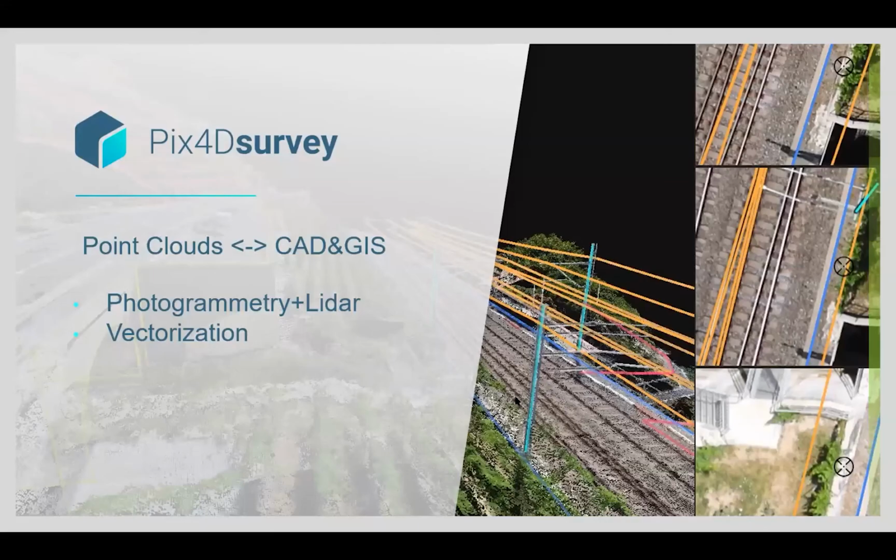Sorry. So yeah, Pix4Dsurvey is a really seamless transition from Matic, like you saw. We actually use all the same file formats, everything. And in fact, if you want to take your project from Pix4Dmatic over to Pix4Dsurvey, you just need to run calibration and the densification. And that point cloud that's created in the background, that's our own file format, so we can already read that directly. You don't even have to go as far as creating that LAS file. That's an optional thing to be able to share it out with anybody else that you might need to.